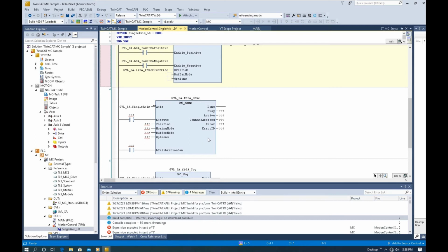At that tooling position, we will define it as 0, or we will define a certain value, for example, 600 millimeters. That position we will directly set. Once this tooling lineup position is accurate, we do not need to care where the actual 0 is or where this pallet will be stopped. So that working position is the position we really care about.